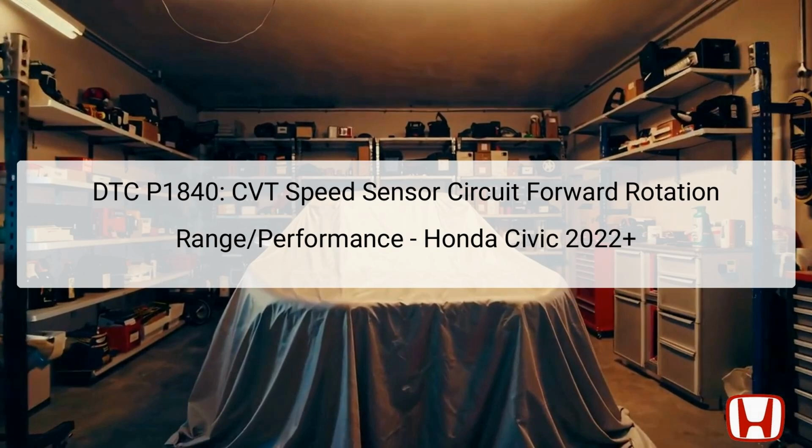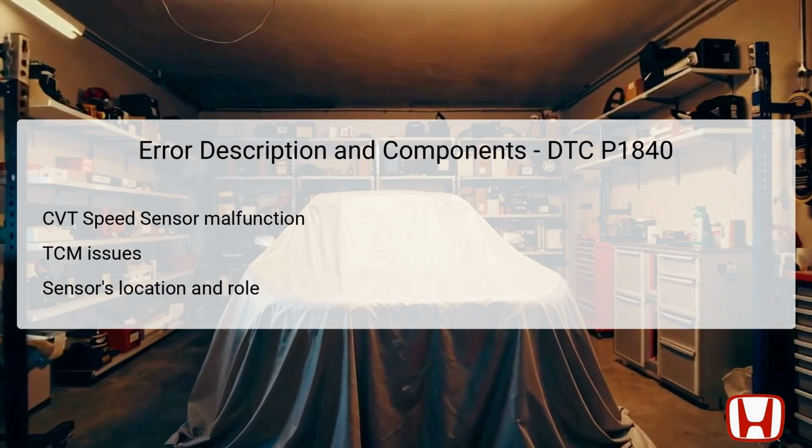Primarily, the CVT speed sensor monitors the rotational speed of the secondary shaft, which is critical in determining the proper gear selection in association with the vehicle's speed. The CVT speed sensor is a critical component that informs the TCM of the rotational speed of the secondary shaft within the CVT system. Located on the transmission housing, the sensor detects the speed and sends this information to the TCM to aid in optimal gear selection. If the sensor fails, it can lead to inaccurate readings, consequently affecting the driving performance.